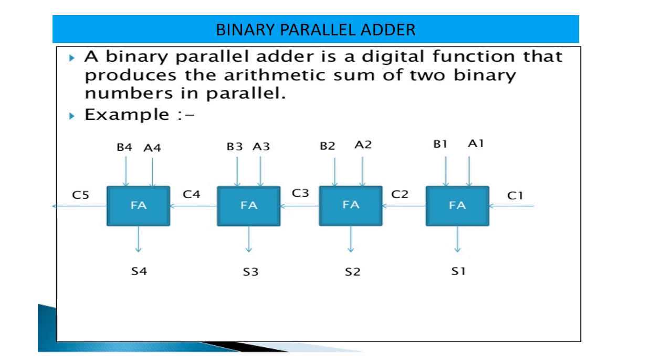When a 4-bit full adder circuit is enclosed within an IC package, it has 4 terminals for the augend bits, 4 terminals for the addend bits, 4 terminals for the sum bits, and 2 terminals for the input and output carries. An n-bit parallel adder requires n full adders. It can be constructed from 4-bit, 2-bit, and 1-bit full adder ICs by cascading several packages. The output carry from one package must be connected to the input carry of the one with the next higher order bits. The 4-bit full adder is a typical example of an MSI function.